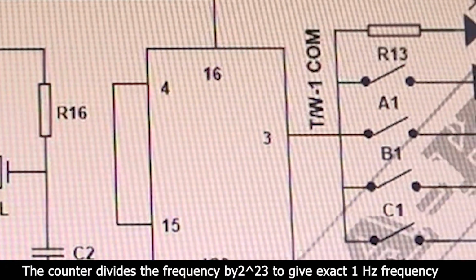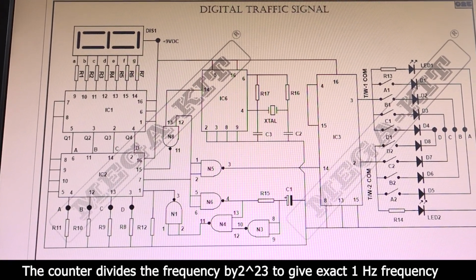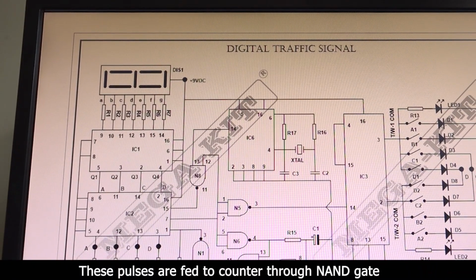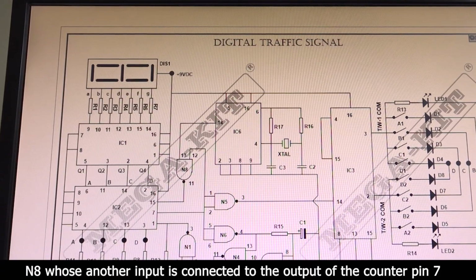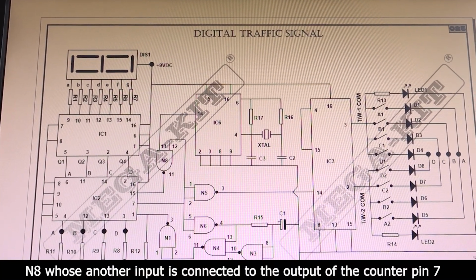The counter divides the frequency 2^23 to give exact 1 Hz frequency at pin 14. These pulses are fed to the counter through NAND gate N8, whose other input is connected to the output of the counter pin 7.